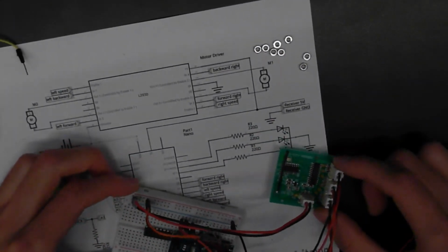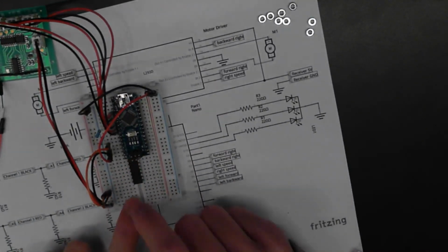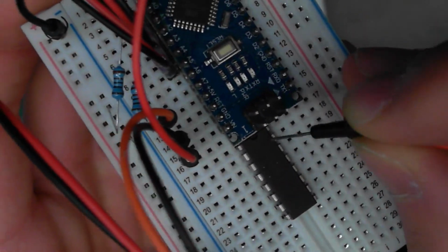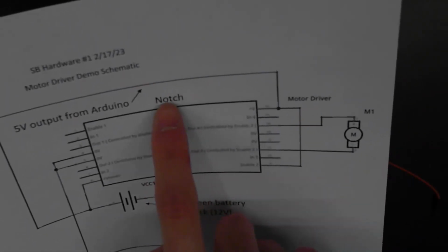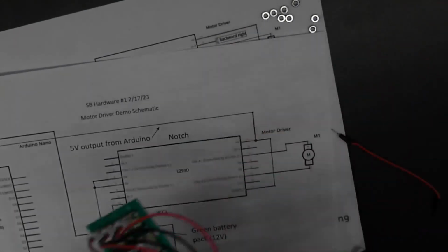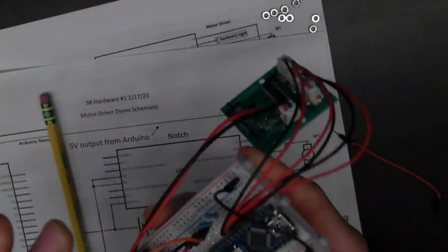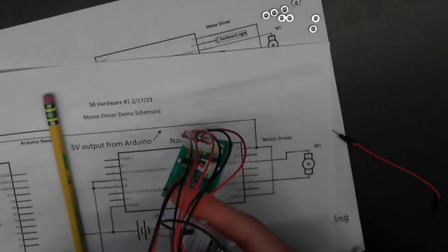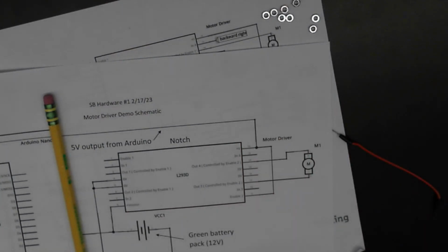So as you remembered from last workshop, these motor drivers are not symmetrical. They do have an orientation. So on your motor driver, you should see a little notch at the top. And that indicates the top of the chip. And on your schematic, the notch should be here. So I think we should face it the other way in this case. It's more intuitive for them. Do a lot of people have theirs the other way? Yeah. Okay, hang on just a sec. I need to rotate mine. Did they have it like here? Yeah. Okay, so like that.